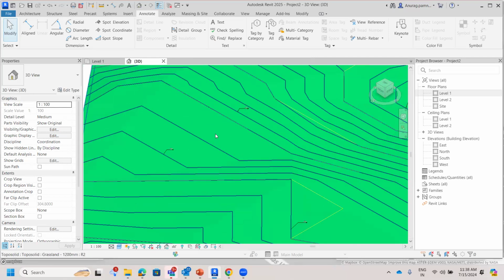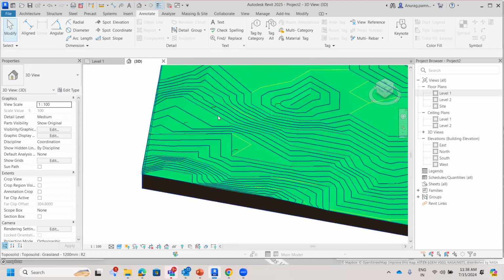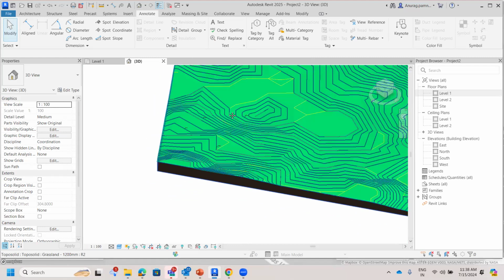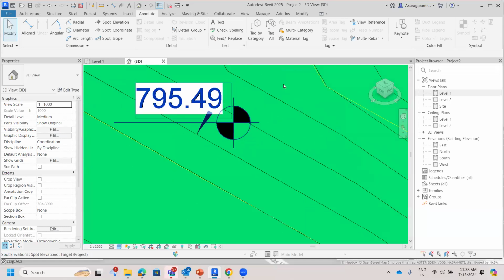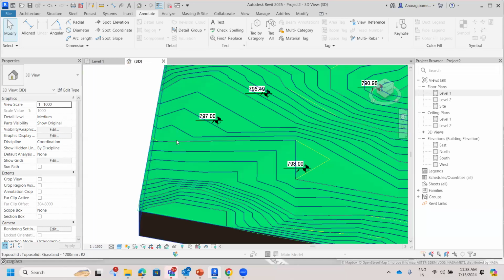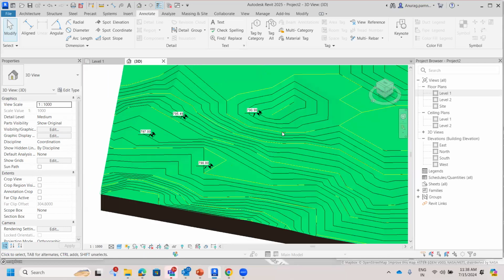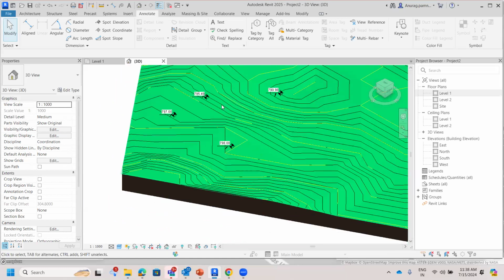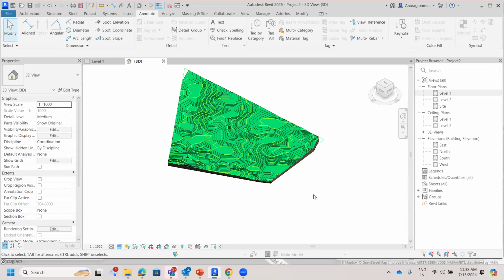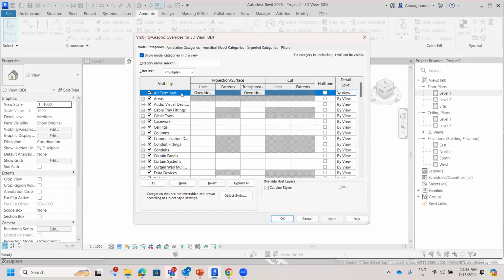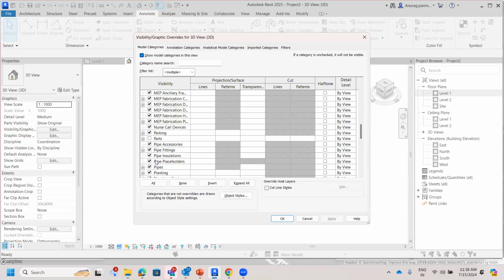So you have multiple levels which have been defined in the CAD, and you have acquired those coordinates over here. If you just need to increase the size of it, just scale it somewhere around 1000 so you can see all those things accordingly. Right now, because I have a certain base point associated with it, and each view is associated with its visibility graphics, I will type VG and it opens the categories of elements. I would be going on to Site again.